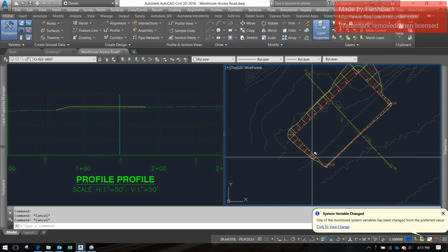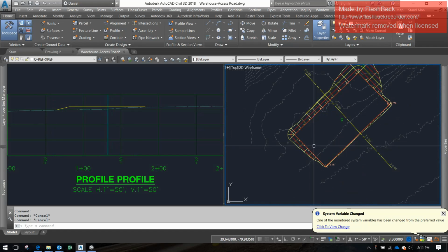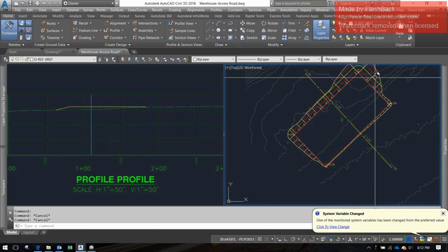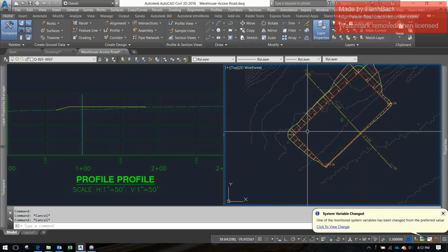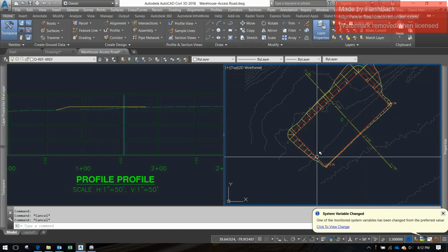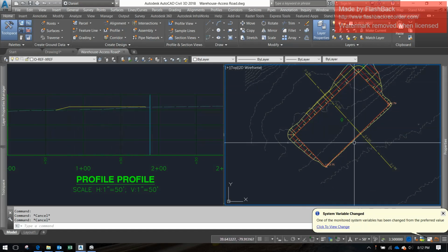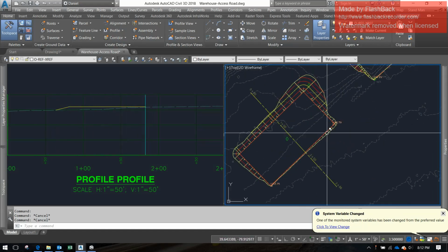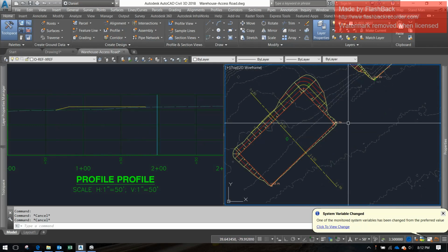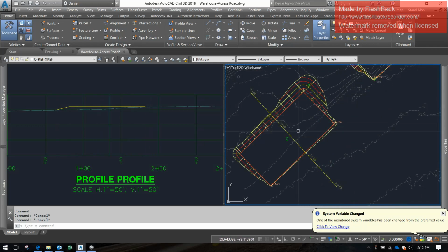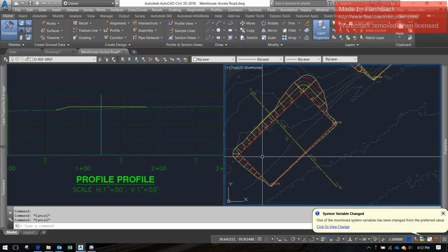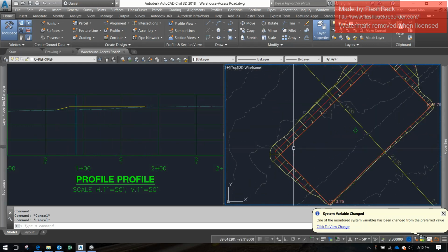It will have a berm, a form of secondary containment aside from the tank that will be used to trap the liquids from spilling out. And the easiest way to do that is by creating a berm around your pads. But the berms have certain criteria on them that allow them to be mountable, meaning that trucks can drive up and over them without bottoming out. So what we're going to do is create a little mountable berm there.